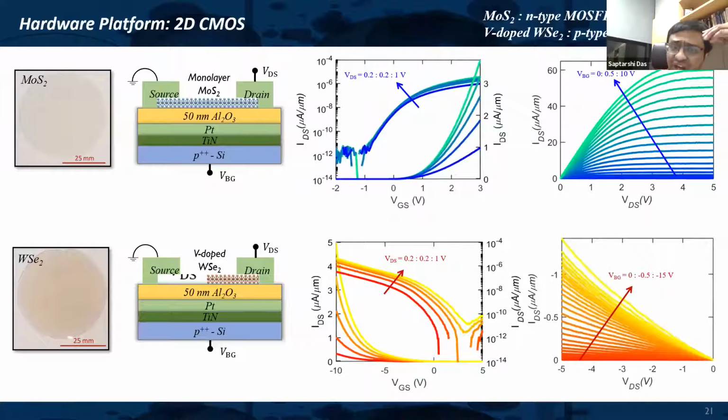Now, 2D materials, as you can see, have primarily been N-type. Most of the exfoliated materials have shown N-type characteristics, with some ambipolar characteristics from tungsten selenide or molybdenum telluride. But there has been a real lack of P-type 2D materials. But now, thanks to my wonderful colleagues who keep growing wonderful materials, we have been able to also grow P-type 2D materials, which is nothing but vanadium-doped WSe2.